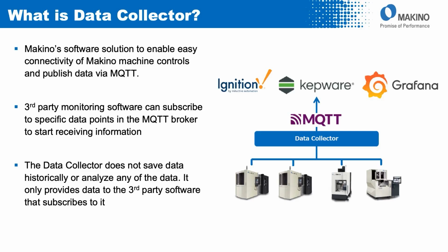At its core, it's Makino's software solution designed to easily connect directly to Makino machine controls. Data Collector takes the rich, machine-level data coming from the control, formats it, and publishes it via MQTT. From there, third-party monitoring or analytics platforms can simply subscribe to the specific data points they care about through the MQTT broker and start receiving information in real time. No custom integrations, no scraping screens, and no compromise on data quality.